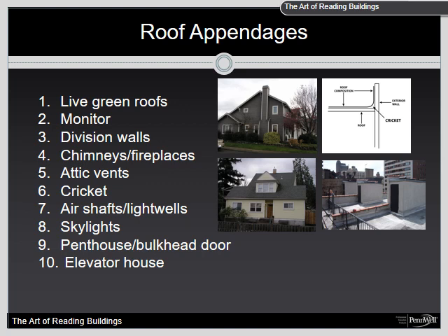Also, with the masonry chimney, you've got to be very cautious in terms of how well is the brick and mortar? Is it one of those older style mortars that is dissolved by water? Do you have loose bricks? If you hit it with a hose stream, are parts of the chimney going to start crashing down to the people below and create some sort of fall hazard? So those are just some things to keep in mind when dealing with your chimney and fireplaces.